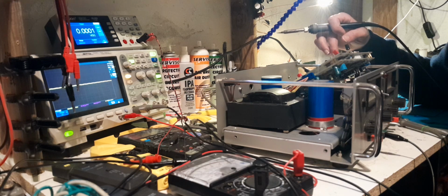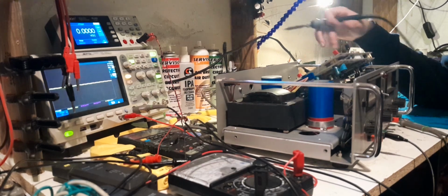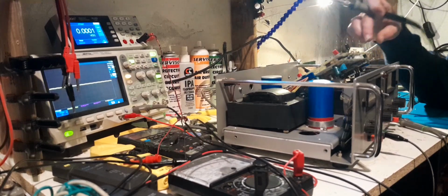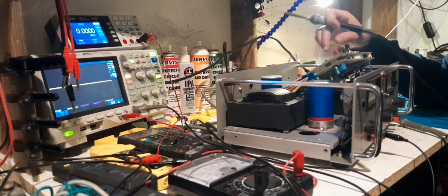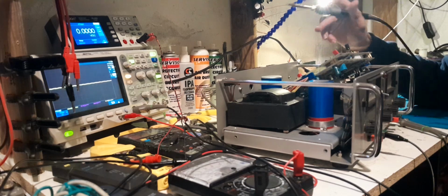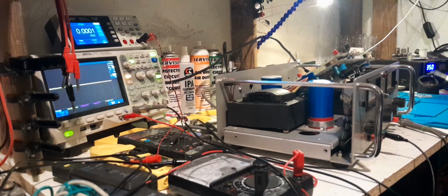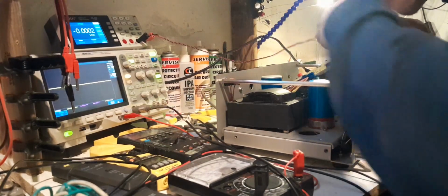Yeah, maybe they have got the reference divided down and going into one input, and then the current shunt going into the other input and a pot across the reference. That actually makes sense, because I remember now when we measured across the constant current pot, I'll show you guys actually, it's got a really small voltage across it. And the constant current reference is 5.1 volts.